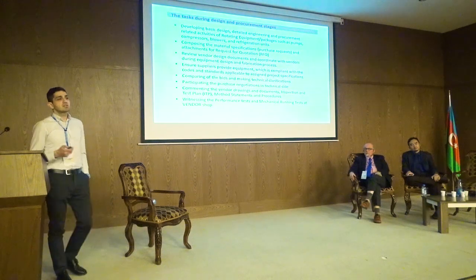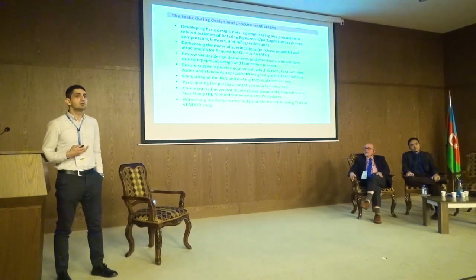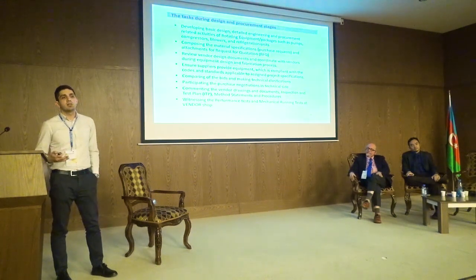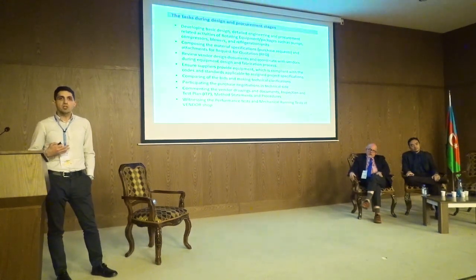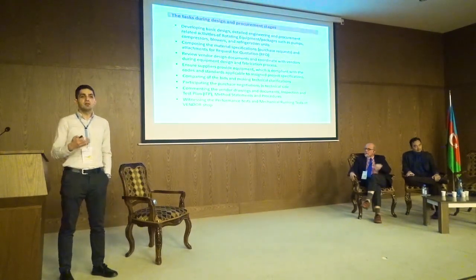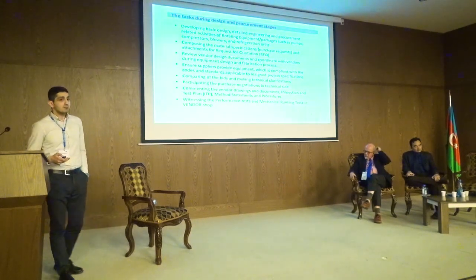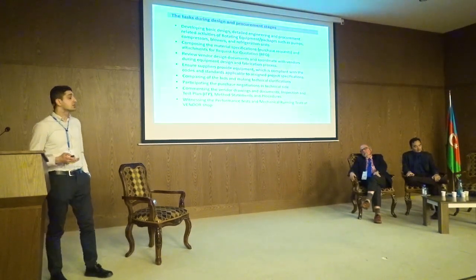And of course, once the vendor has been selected, then the rotating equipment engineer during the project phase can also make some workshop visits, can go to the vendor workshop and witness the performance tests and some other inspection tests.